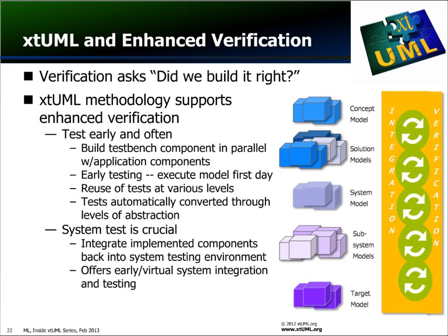And in support of system test, the initial system-level test bench can be used as a virtual integration platform in which to integrate implemented components back into the system testing environment for early and ongoing virtual system integration and testing. This, by the way, is not only supportive of certification goals, but can really provide a huge productivity gain as well, catching critical integration issues at early stages of design where they can easily be remedied, as opposed to the typical late-stage integration testing where issues found could be crippling to the program.